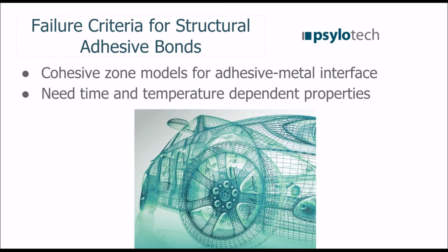So we were approached by a large automotive company not too long ago, and they were trying to figure out better ways to simulate the bond between the frame and the different frame components. So a fracture mechanics model was needed to simulate those well. We ended up looking into cohesive zone models, which have been around since the 60s. They're pretty well developed in the literature, so we decided to go down that route. An addition that we wanted to add to it was time and temperature dependencies of these fracture mechanics. So that's kind of where the work is going.